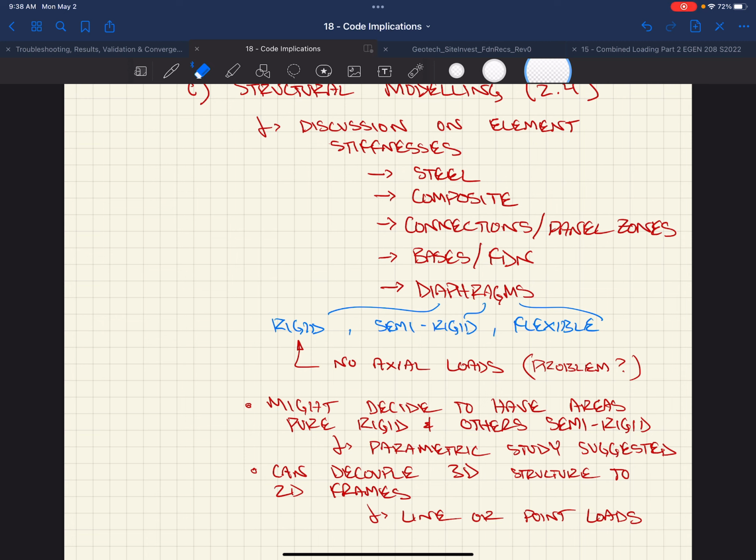Well, what is the long story short? What do they say? Well, hey, by the way, if you do a centerline to centerline approach, you're going to pretty well model that behavior, the panel zone. Pretty sick, right? You don't have to do all this crazy stuff that you might have thought you did, okay? But they do talk about the fact that you can change that performance and behavior with these connections and the panel zone stuff.